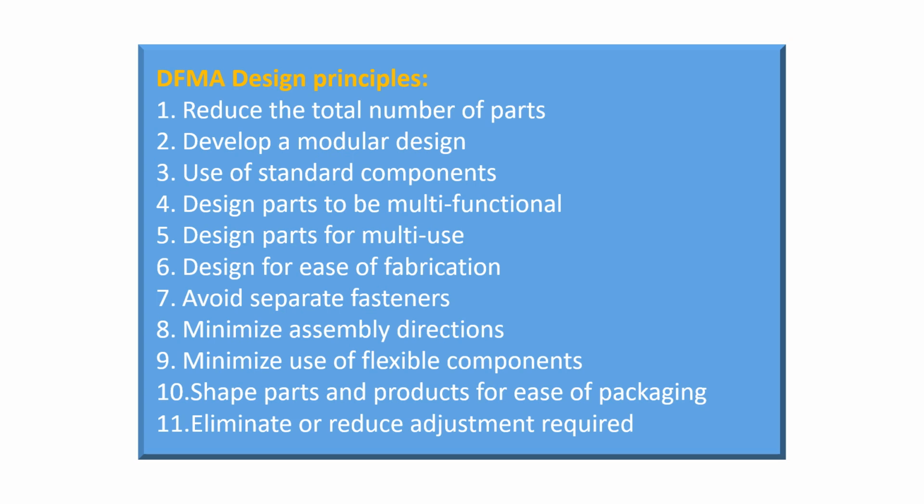2. Use a modular design. Each subassembly should consist of 5 to 15 parts. Maintenance and repair are easier. Automatic and manual configuration is then easier. Stock requirements are reduced. The final assembly time is reduced.